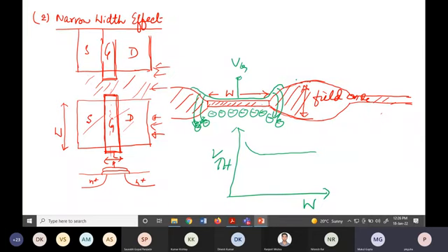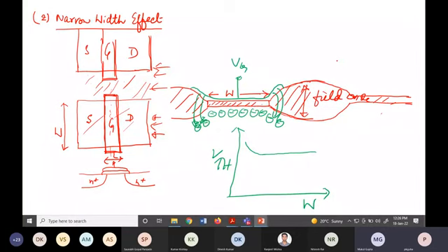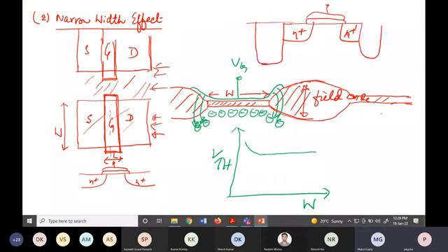I don't want to go in that direction, but the way trench isolation works is, I think, extensively discussed in some technology class. But let me just tell you, in case of trench isolation, if this is my n plus, and then instead of field oxide like that, you will have trenches. Trench here, trench here. Trench means you create a trench, and then you fill it up with oxide, right?